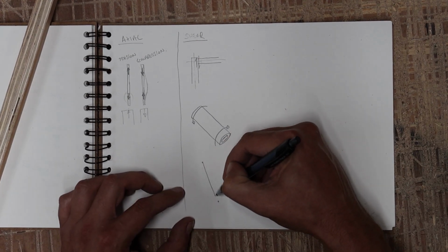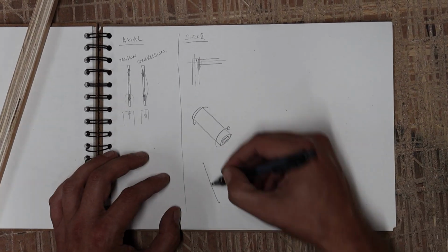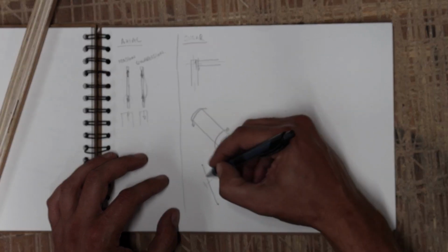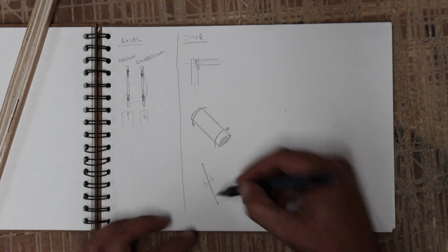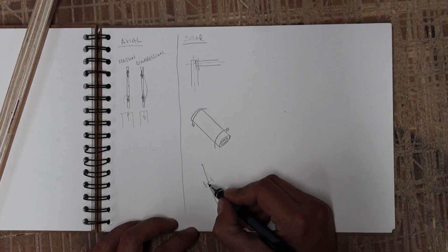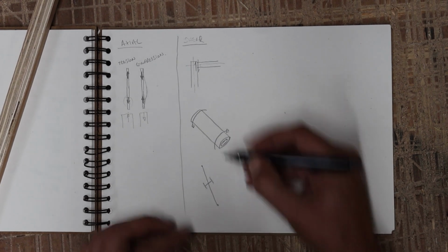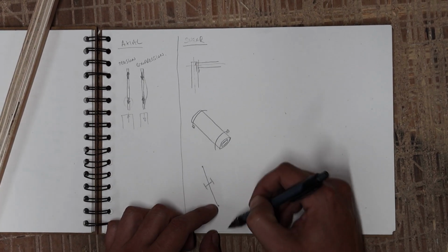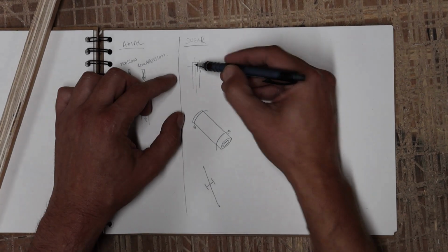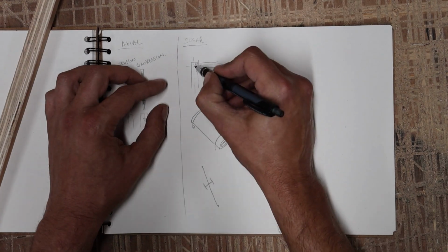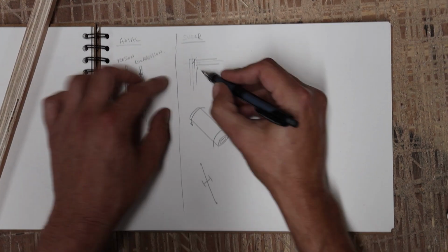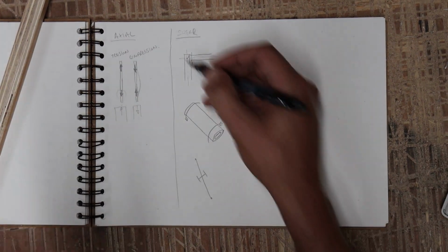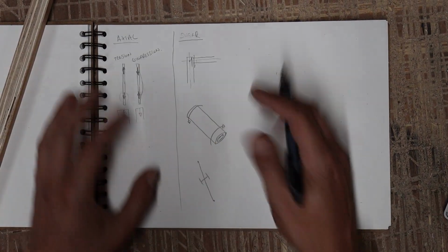We join them with a line, and then we tell the computer what that line actually means, so that represents the beam that we're using for that line. It doesn't actually exist in the computer as a collection of shapes. It just exists as a line. So when we define that line, we want to use the center line. If we're using the center line, then because the pin is here, we actually generate a small amount of moment here. I think I've probably gone too far.